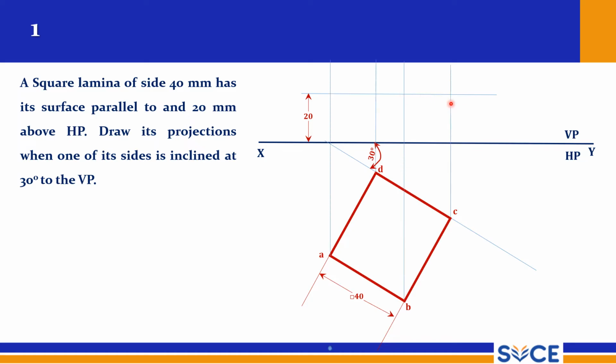So you draw the projectors, and this point is A and this point becomes D. D is within brackets, so this D is not visible, and B dash is visible, and C dash is also visible. From A dash to C dash, you should draw a thick line. So this is this maroon color, right? Those lines should be drawn with thick lines. So this is how you should solve this problem.